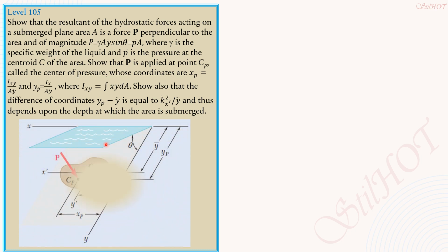So here is the given figure in general, and we will call the distance from the differential element. For our solution, we have a differential element dA here, and it is where the differential P acts, and the distance along the plane of the area to the liquid surface that is exposed to the atmosphere is y, so that the vertical distance from the liquid surface down to the differential area, because this angle is also theta in the figure, is y sine of theta.